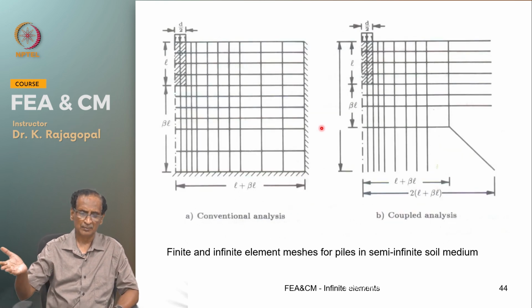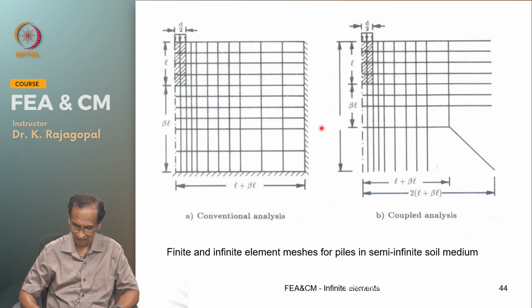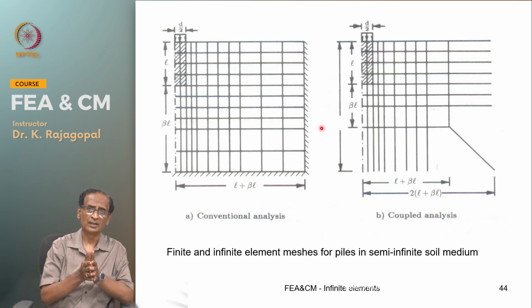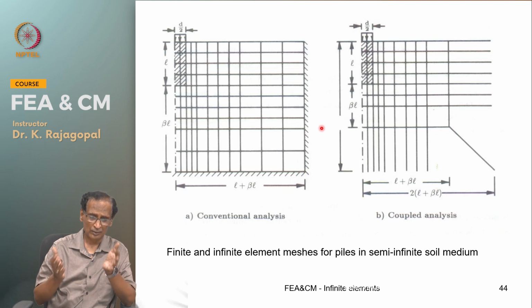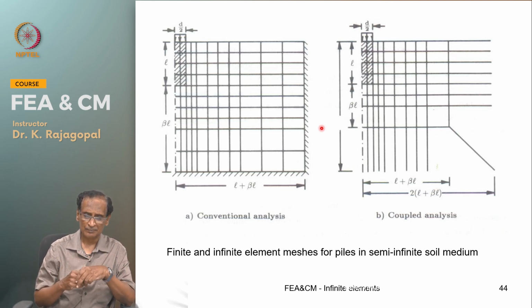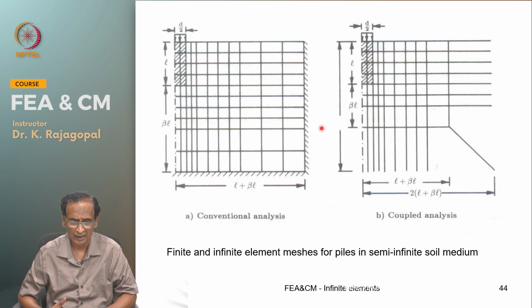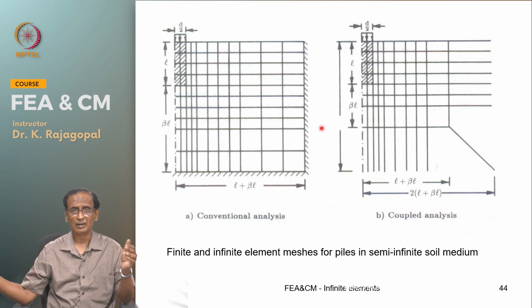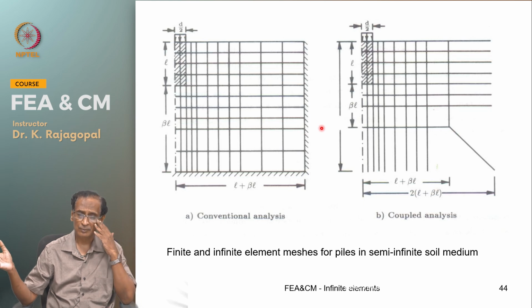And you can do the same thing even with pile foundations, and especially when you have a very long pile foundation, it's hard to decide where you need to keep your boundary, because the pile length itself could be 30 to 40 meters, and beyond that how much soil we need to place, either 1 times, 2 times, half a time, and so on.